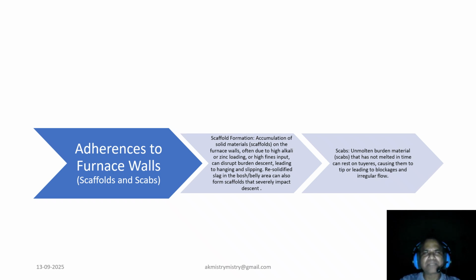And as we recently discussed about a chilling trend, it causes thermal instability in direct reduction, an increase in direct reduction consumes coke, accelerating the burden descent and driving the cohesive zone downward.